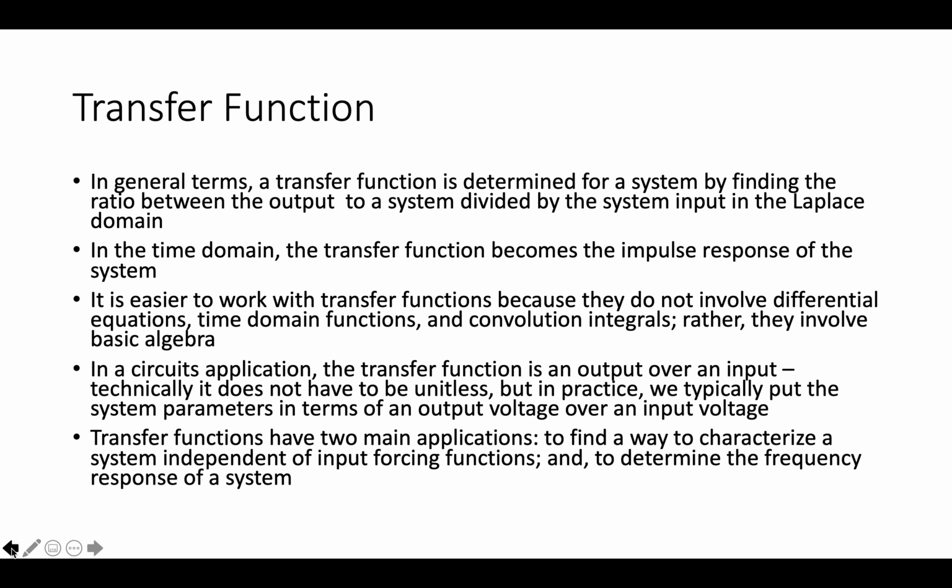So if you have this way of characterizing a network just from its passive elements, then you get this function, and all you have to do then is multiply it by the input voltage. And so the input voltage could be changed. You could find the response of the circuit to a sinusoidal voltage, to a pulse, to a series of pulses. So anyway, that becomes very convenient.